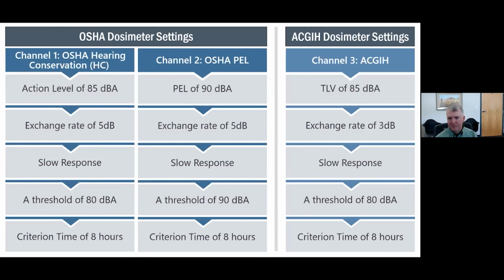It's always going to be a bigger number than OSHA, because mathematically, it's actually accurate that, let's say, a 10 decibel increase is a little over 3 times louder. And again, from a physical and mathematical standpoint, that is correct. Whereas OSHA is saying, well, we're using a 5 dB exchange rate, and it's only twice, you know, it's every 5 decibels. Still slow response.